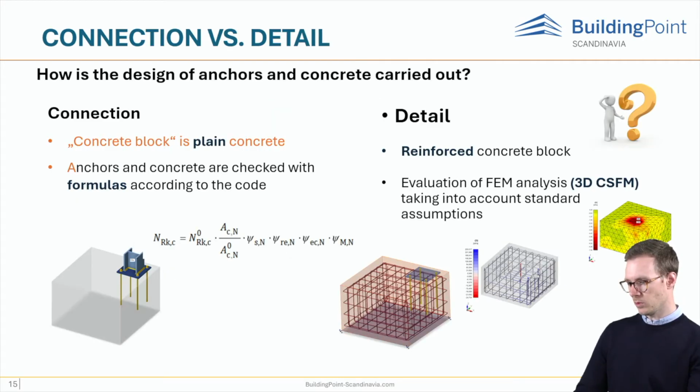And to make this even more clear, we have some clarifications about the differences between the connection and the detail application. So the first one is, how is the design of anchors and concrete carried out? Well, in the connection application, the connection block is considered as plain, unreinforced concrete. The anchors and concrete are checked with the formulas from the code. And in the detail application, the concrete can be reinforced. And in fact, it must be reinforced.